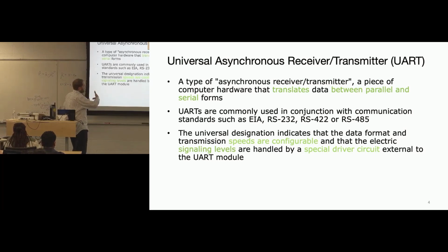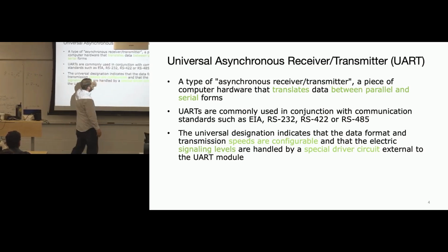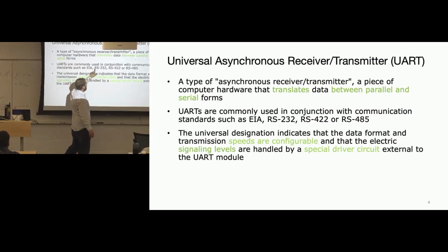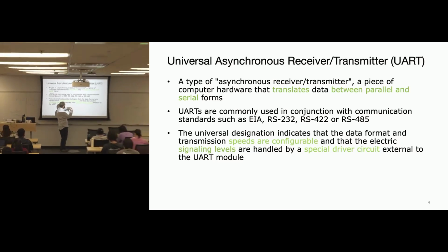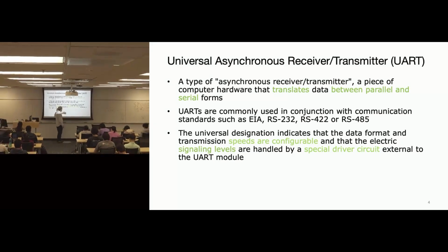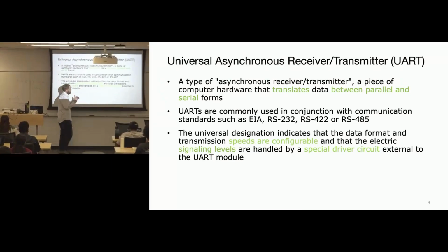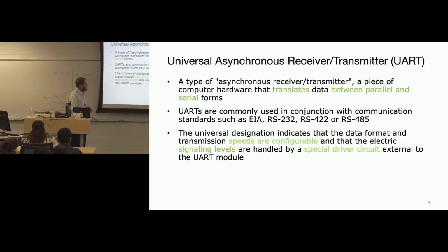They take the massively parallel world of the microcontroller or the processor and shift the data out one by one. There's a bunch of standards around this. We're going to talk about UART, and these are the physical interfaces for a UART protocol, which define both the mechanical interface, the connector, and the signaling interface, like the voltage levels of the signal, and the data rates.